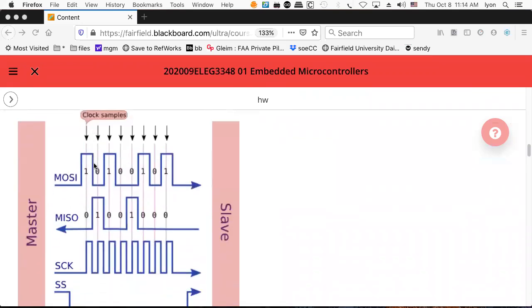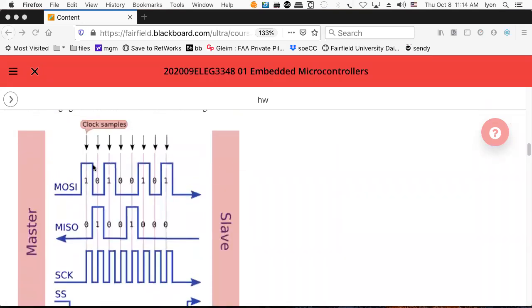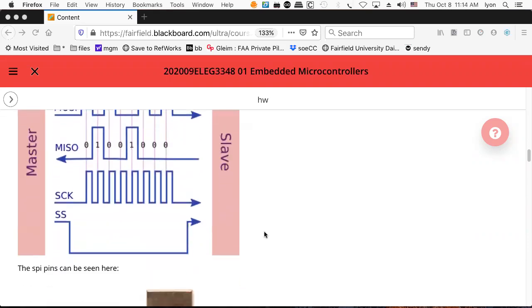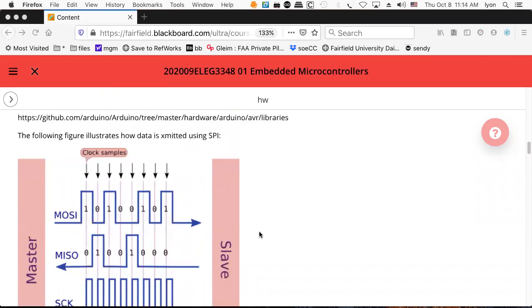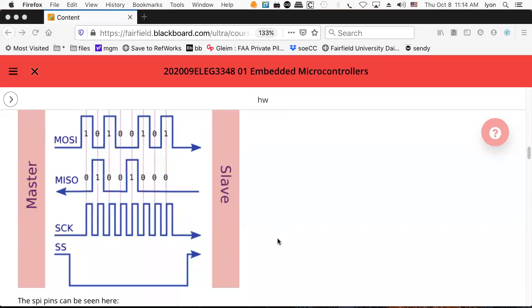And so, you know, one thing you can say about the SPI is it's extraordinarily fast. It's full duplex. The serial clock for the actual SPI interface has a minimum of divide by 2 in the prescaler. So for our little 16 megahertz Arduino Unos, it'll probably be running at about 8 megahertz, which is about as fast as that Arduino is going to be able to take any data anyways. But if you had a faster computer, SPI will run faster. And if you have a 64 megahertz clock in your little CPU, this thing will probably run at 32 megahertz. And so that's nice.